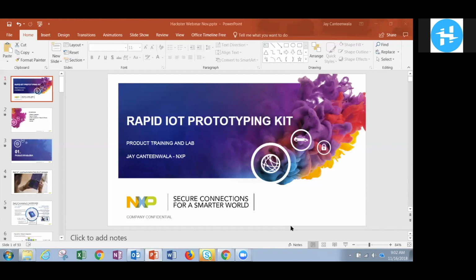Can we connect Raspberry Pi with the docking station? I would say that you can connect the Rapid IoT to the docking station, and through the click headers, you can wire the signals to the 40-pin connector of a Raspberry Pi 3. So you can indeed connect a Raspberry Pi 3 through wires between both headers.